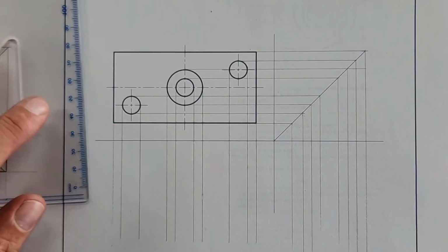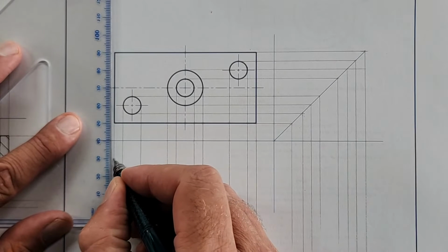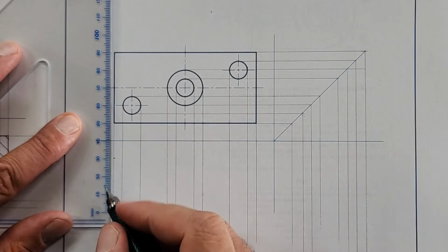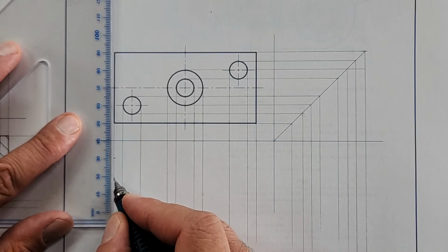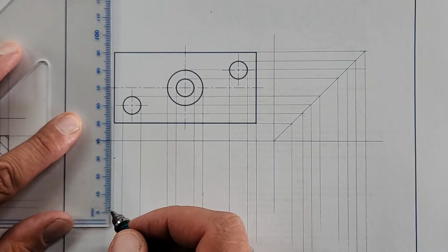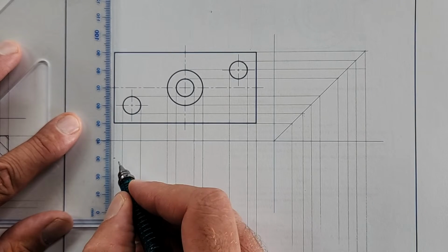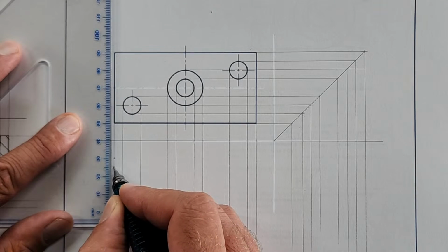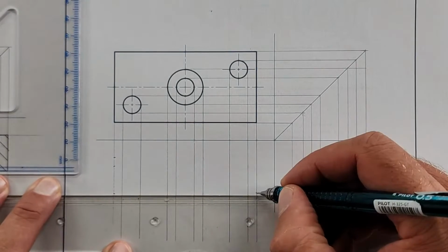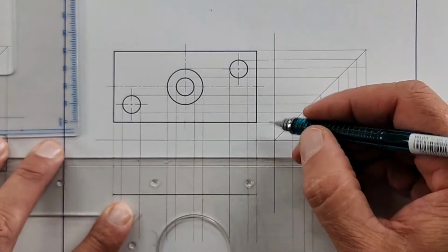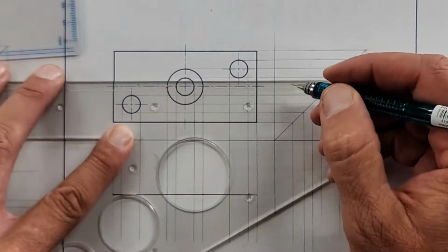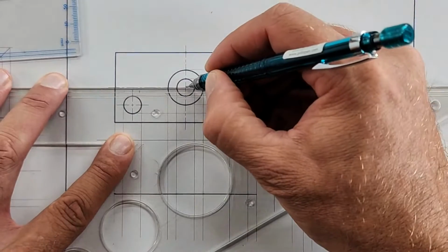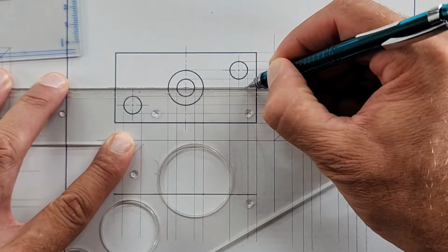All right. Yes. Scale 1 to 1. We're going to have a 10 millimeter gap first, and then they say 10 and 15. There's a measurement wrong. That must be 20 and 15. Okay. Just double check there. That's 20, and that's also 5. So there's a mistake there on the actual drawing. So, okay, let's do the cutting plane so that you're all with me. I'm going to just draw it in. There it is, going all the way.